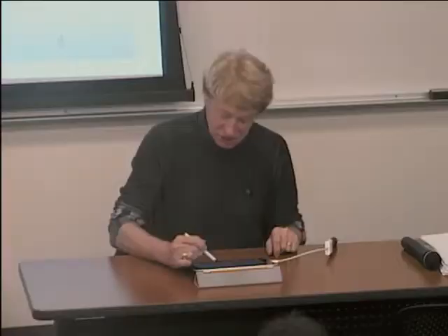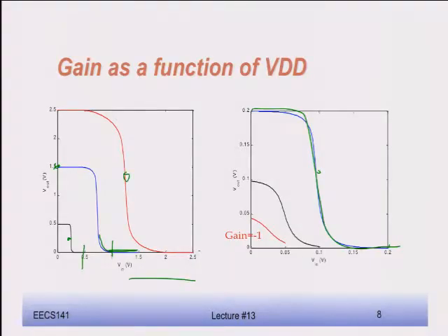Why do you think that still could work? Turns out if I go lower than the threshold, like here, 0.2 volt, I still get an inverter. Quite impressive. I'm basically operating my devices at voltages below the threshold. They never turn on, and I still get a voltage transfer characteristic which is quite beautiful. Actually, there's a decent gain. It's not as good here. Here I have a gain of about -20 or something like that. Here the gain is maybe -5 or something. But still enough.